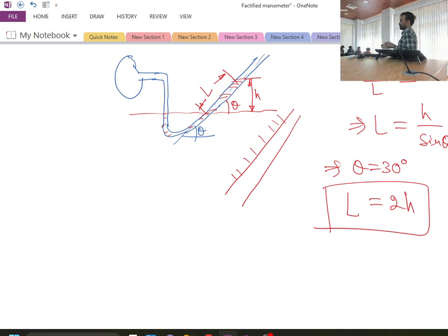If you have a submarine, the different structures of its outer body are subjected to pressure force from all the directions. So determination of that pressure force is very important because it helps in the structural design of these solid structures as well as in the stability of the solids. Because if the forces acting because of the fluid pressure are unbalanced, then these structures will have chances of collapse. If structures are floating, then there will be chances of unstable behavior of that system.